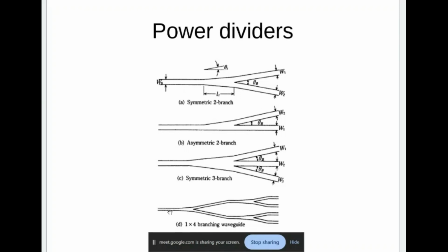So it appears very straightforward, simple functionally, but the design or the functioning is quite involved. I will highlight one or two points. There is a corner here, a sharp edge. It's not very good for optics. The mode propagating will be disturbed by that. And you can also see a taper. Here the width is W and here the width is 2W. So if you are propagating a mode, depending on your design, it can become 2 modes. Sometimes you can use it to advantage also. So these are all the things.